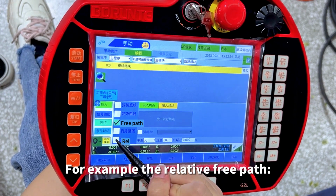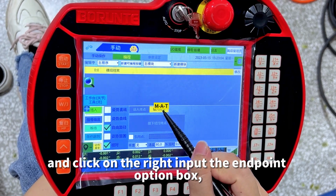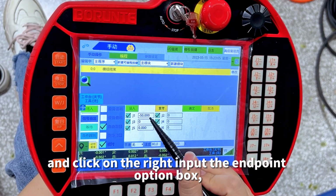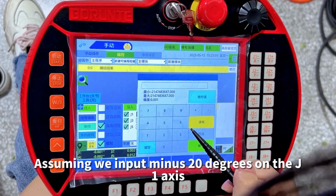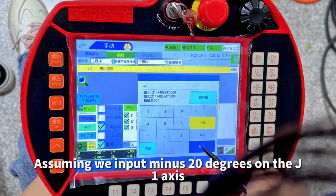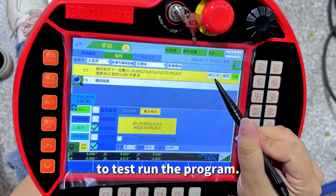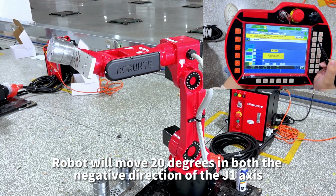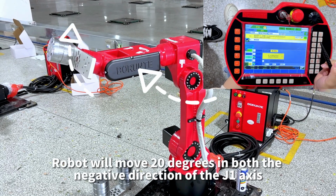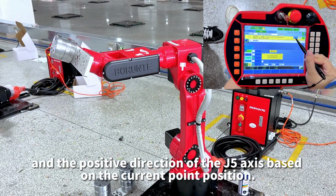For example, the relative free path. Tick relative and free path, and click on the right input the endpoint option box. Here will appear the setting of J1 to J6. Assuming we input -20 degrees on the J1 axis, and input 20 degrees on J5 axis. To test run the program, the robot will move 20 degrees in both the negative direction of the J1 axis and the positive direction of the J5 axis, based on the current point position.